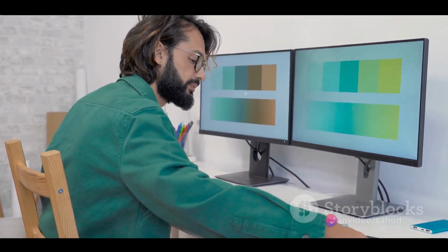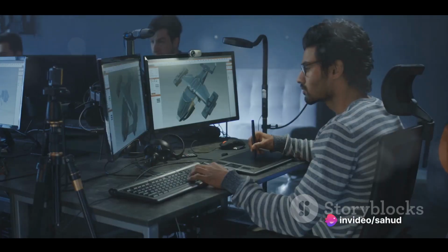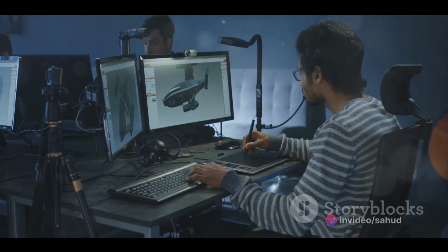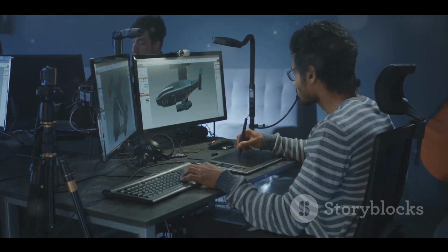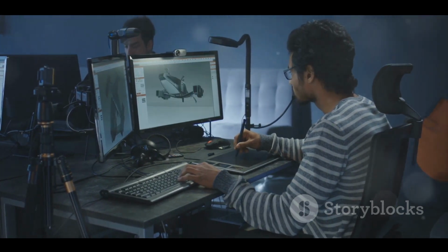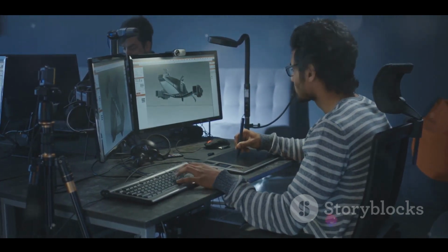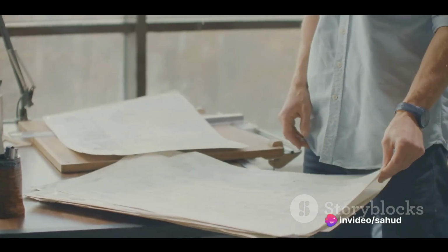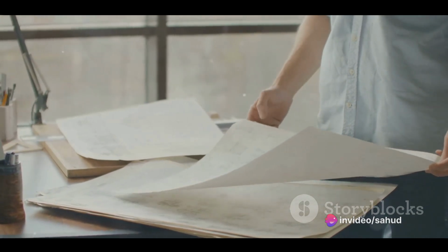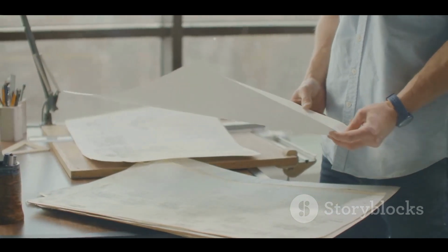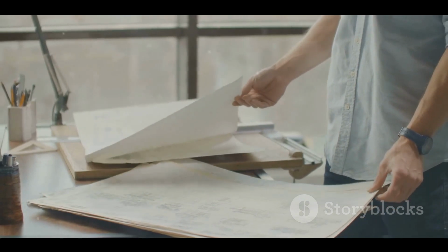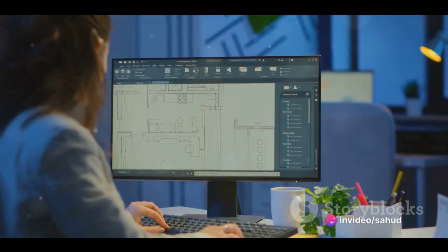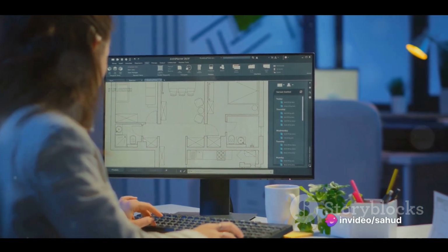Another common problem is sketch entities disappearing or not displaying correctly. This can be due to your graphics card or display settings. Try updating your graphics card drivers or adjusting your display settings. If the problem persists, it might be a software issue, and you may need to reinstall Solidworks. Finally, if you're having trouble with tools or commands not working as expected, make sure you're using them correctly. Refer back to the software's documentation or seek help from the Solidworks community. There's a wealth of knowledge out there, and you're never alone in your struggles.